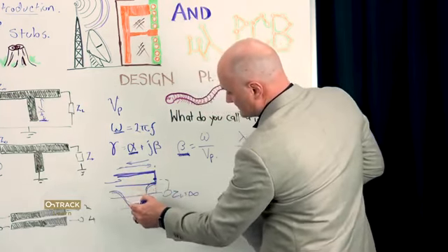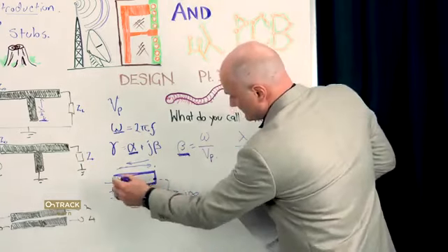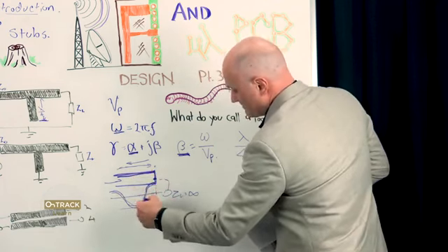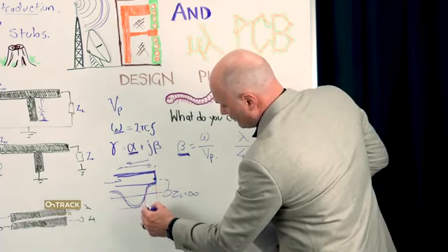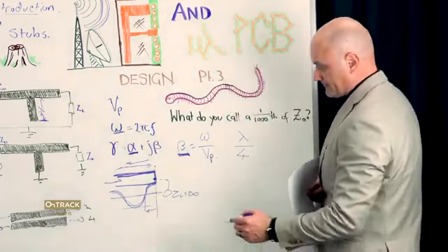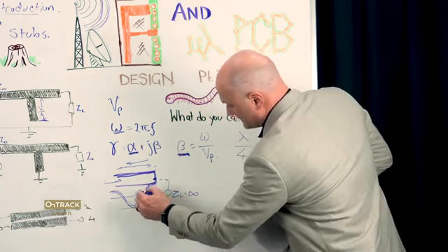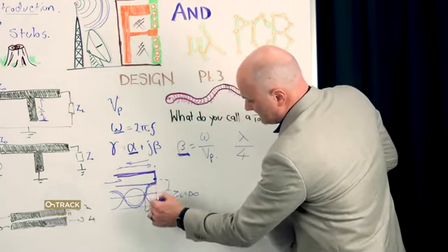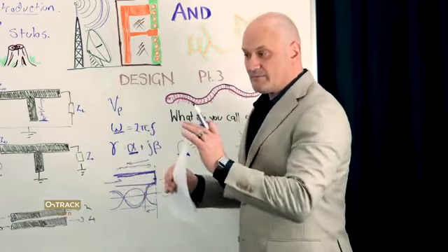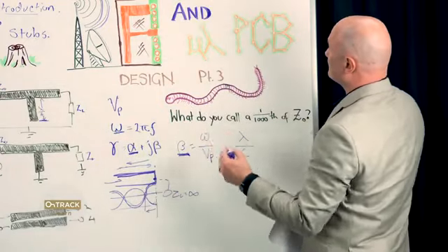So you have this standing wave that occurs. We'll talk about that more in a moment, where this chunk of transmission line is reflecting all of the wave energy back, and at a quarter wavelength back from that open circuit, the voltage stays at zero, because we end up with a standing wave that goes up and down as the forward wave and the reflected wave add up and cancel out, or add up and double, but create a standing wave.